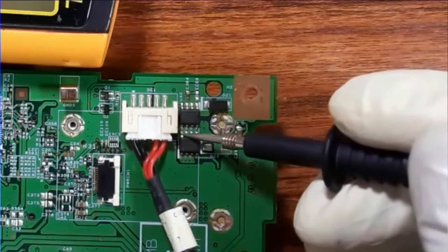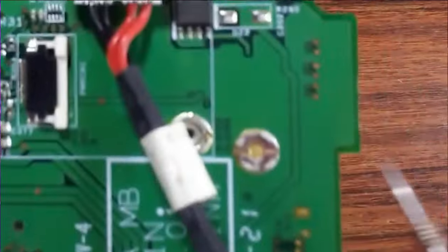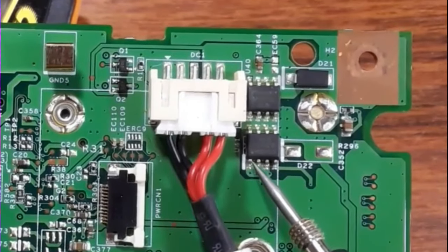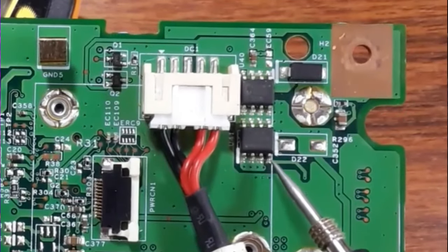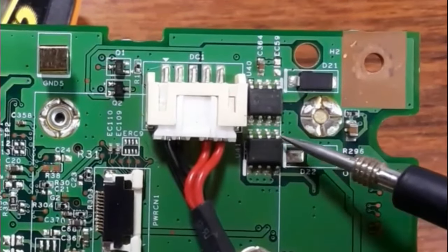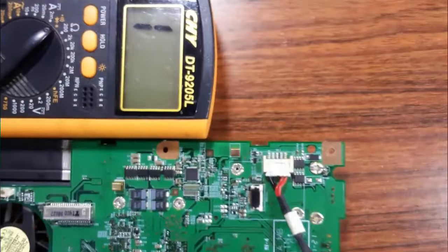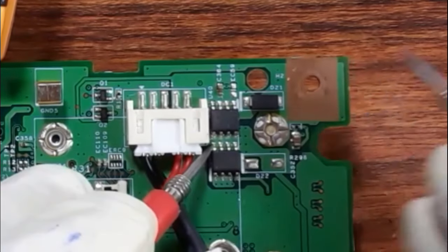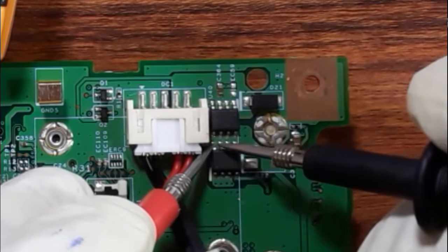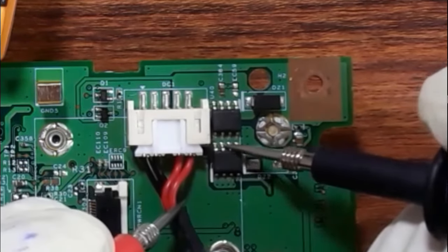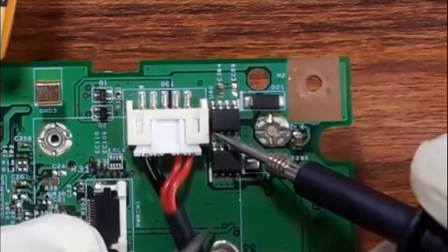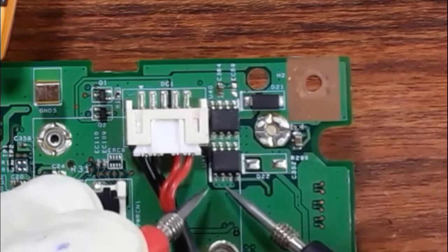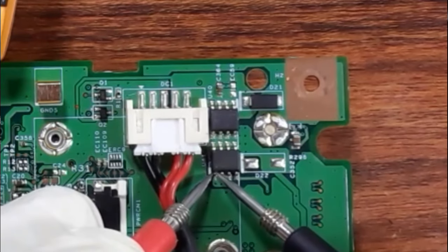So let's check what we have here. So if you focus also here, we have here the point. The pin number 1 is here, means this is the source. These 3 pins are source, and we have here the drain, and these 4 pins are drain. So let's check if these pins are drain or not. So let's check the continuity another time. So okay, this is 1, 2, 3, 4. So all these pins are connected together. So the drain of this MOSFET is connected to the drain of this MOSFET. Okay, and of course here we will get here a source. So this is the first pin.